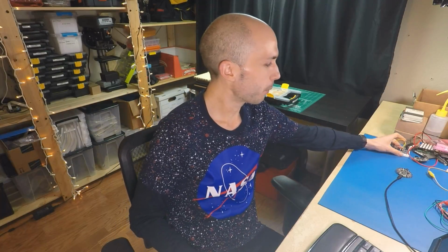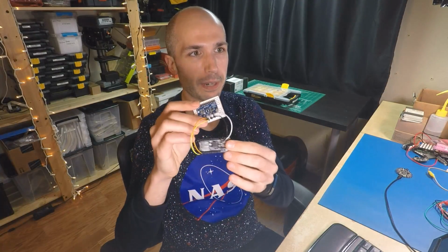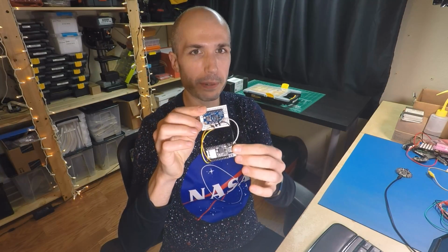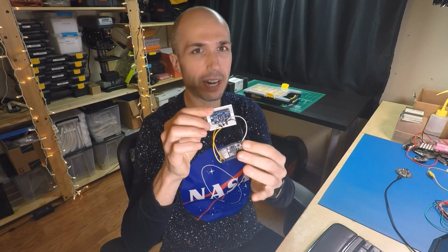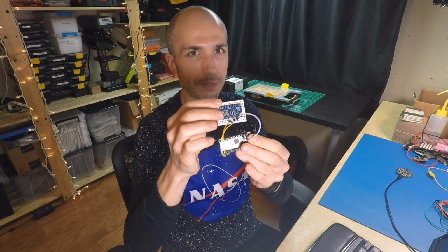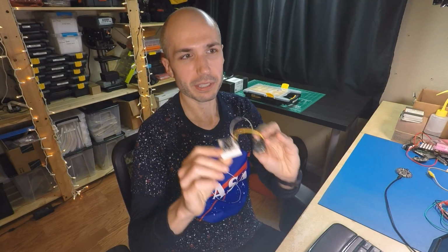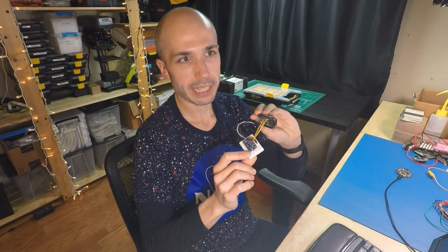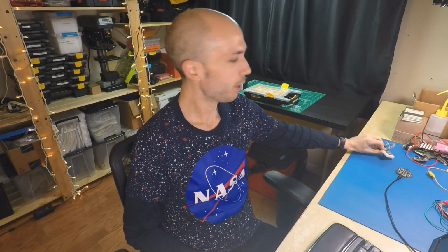But what I was thinking we'll do in this video stream is I'll actually port our MPR121 capacitive touch sensing breakout. It's a little breakout board right here. This is the Feather M0 Adalogger on the bottom here, so it's our Feather M0 board. But again, this is the board you can buy right now that does not have that extra flash memory chip on it. And then on the top here is the MPR121 capacitive touch sensing breakout. This is nice in that you can connect a little breakout board like this to any Feather M0. And then I'm going to write the code in this video stream to talk to that MPR121 capacitive touch sensing chip, and it will do the same functionality that's built into a chip like this.